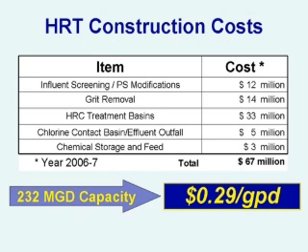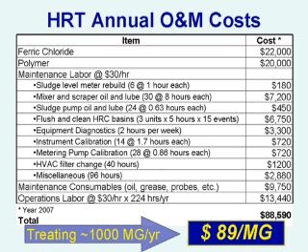So the performance effectiveness study is a 2-year ongoing study that is being performed. It is going to be added to with an additional study to evaluate effectiveness in removal of other constituents of concern in wet weather discharges, including viruses and pathogens. And the exact scope of this study is currently being worked on between the city and EPA. The facility continually undergoes an optimization process for chemical dosage, for enhancing the coagulation and settling, but it has been tested up to 390 MGD, which is essentially the maximum capacity of the influent to the plant.